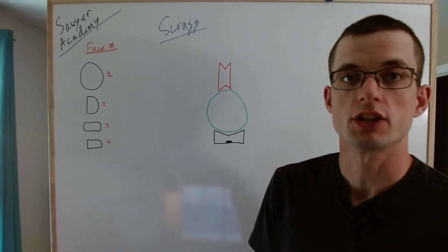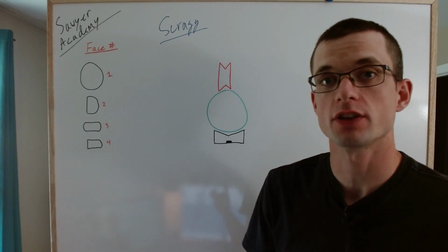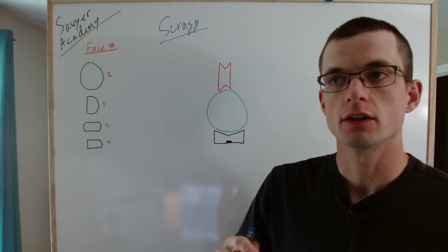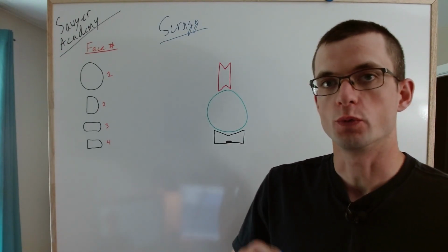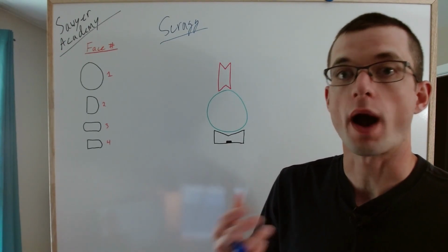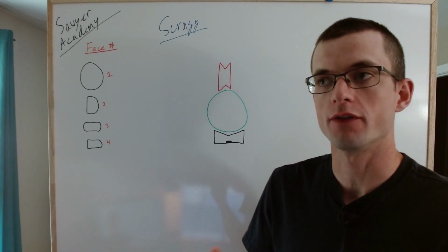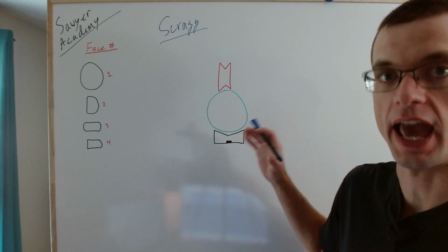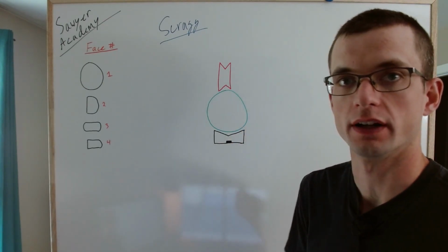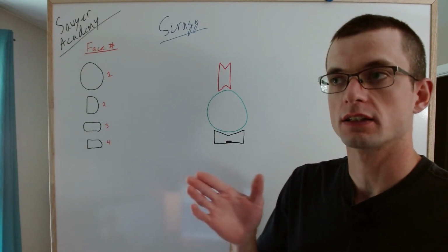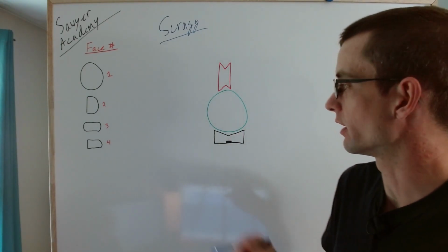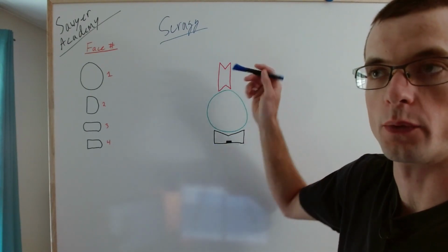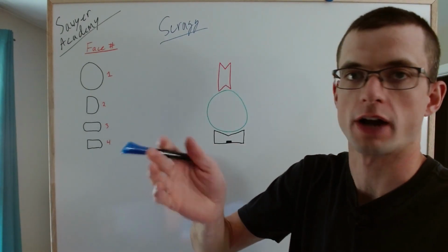One last thing that I want to touch on is taper in a scrag sawmill. In a scrag sawmill, you will rotate your logs, or you can rotate your logs. You won't apply any taper. Why that is, the setup of a scrag mill, or the theory behind a scrag mill, is the logs, this is the end view looking down the length of the saw line. The logs are loaded onto either a sharp chain or a V-flight chain. As well, they're held from the top with press rollers, and those press rollers sometimes are hourglass shaped.